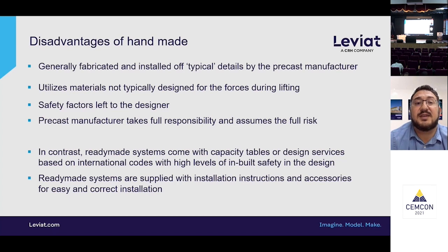They utilize materials that are not typically designed for the forces during lifting. The safety factors in the designs are left to the designer or to the precaster, whoever is responsible for those details. And most importantly, the precast manufacturer, if using a typical detail that they regularly use, takes full responsibility and assumes the full risk.